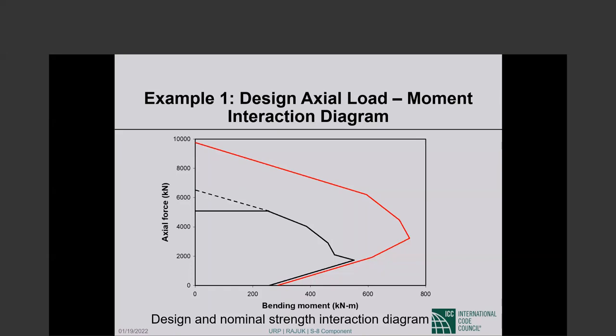That may have an effect on the floor members that frame into those columns. This should be checked out. There is no prohibition. This is something that you can run numbers on, but this is something I would like to check out before proceeding with something like this. It's a problem of possible differential shortening. That's what we call it, differential shortening, particularly in the long run.